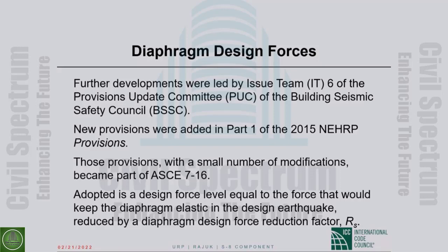So, how to design podium slab to resist huge lateral loads? They are sometimes feet thick. Feet. If it is a tall tower sitting on a podium, you can have a 5 foot thick slab acting as the transfer diaphragm. So the design is no different from that of other slabs, but you have a lot of shear in the diaphragm, and even with reinforcement, you need a lot of thickness.